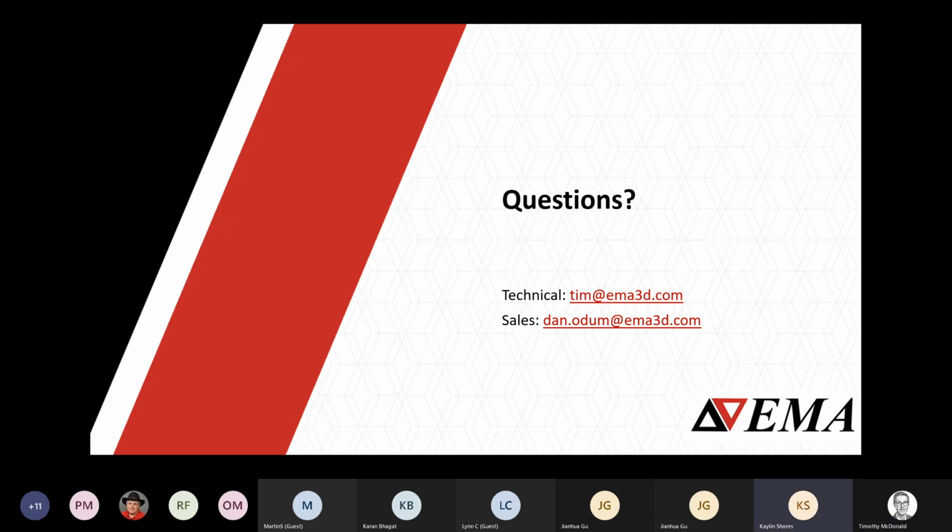All right, next question. What are the steps to import from SI Wave? Sure. So whenever we're running an SI Wave simulation, with just a few clicks, you can capture the near fields in SI Wave. To do that near field simulation, literally it takes 60 seconds, 2 minutes to model the near fields. The user specifies the frequencies, they specify the distance away from the board, and SI Wave's near field simulation is really fast. And so you right click on the results and there's an option to export the near field data.